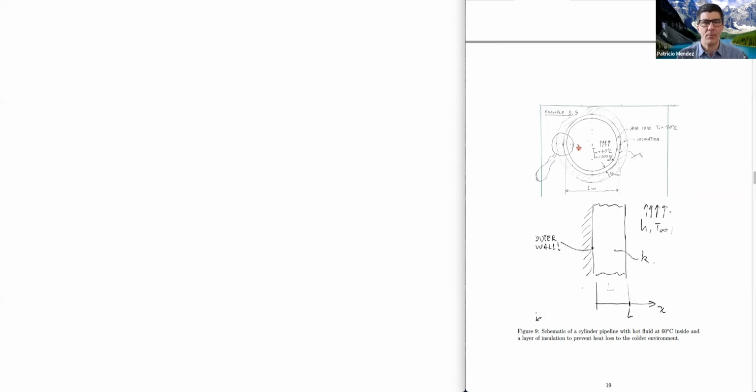If this was a problem of thermal resistance, we would know that the error was thickness over diameter. So 4 centimeters over 1 meter is of the order of 4% error. I'll take it. You don't know thermal conductivity with that accuracy. So that's one thing. Here's another thing that the book does without telling you, but it's very important.